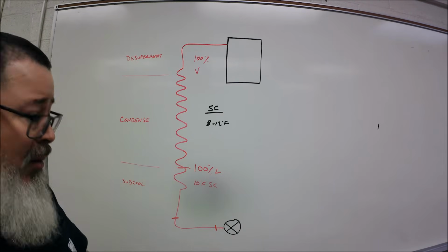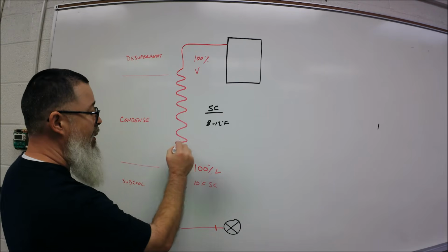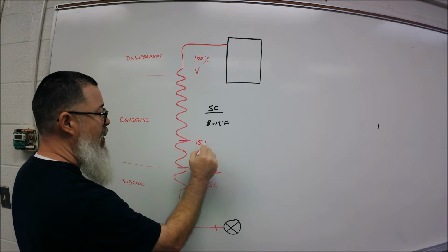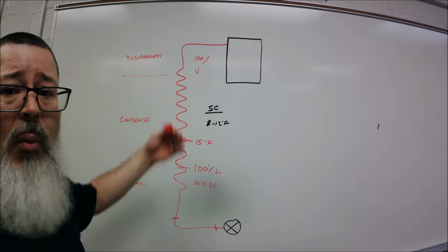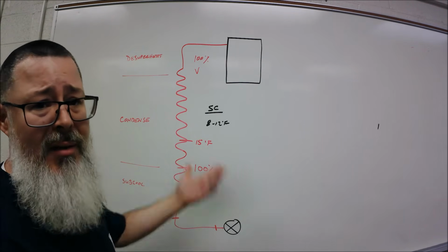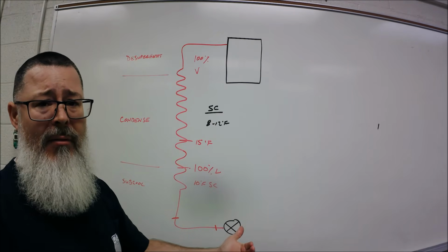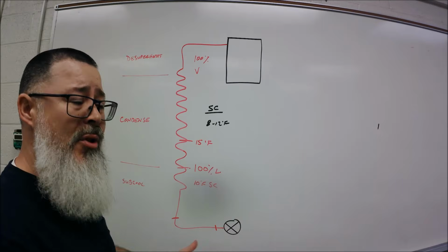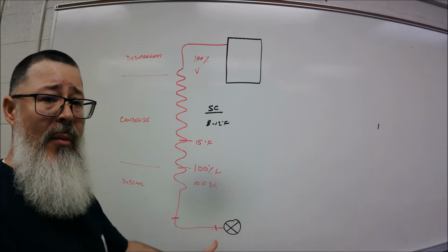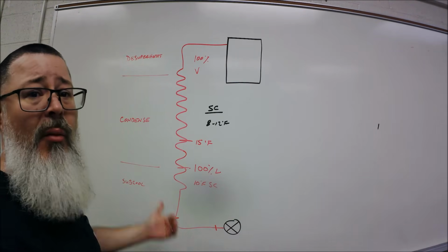What about 15 degrees of subcooling? Further back, right? 20 degrees, what have you. And of course, this is not the spec, this is an idea. The higher the number, the more liquid you have, and the further away from that metering device you're filling up with liquid. I hope that made a little bit of sense.